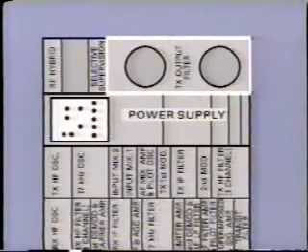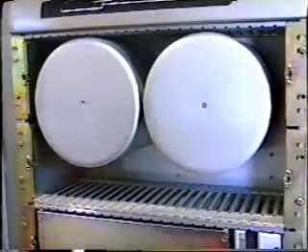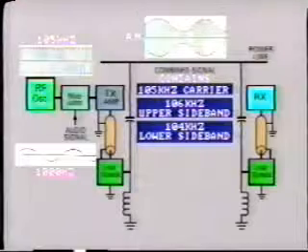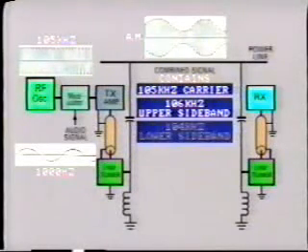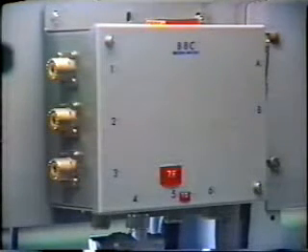This next module, the transmitter filter, is a tuned circuit that passes only the transmitter's specified frequencies. With an SSB carrier, the filter blocks the lower sideband and carrier frequencies, allowing only the upper sideband frequencies to pass through. Incidentally, some single sideband units may retain the lower sideband and reject the upper, along with the carrier. The filter is provided with an impedance matching transformer with taps on the output.